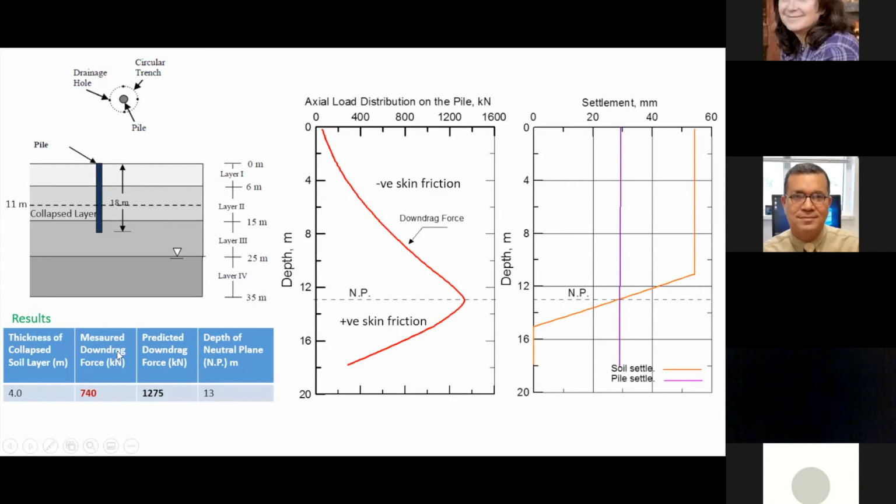It's larger than this. Of course, there is another reason that specialists in geotech understand. We have arching effect here. The deeper the soil, the less settlement that you can carry to the ground surface. This is another story that could affect the results here.